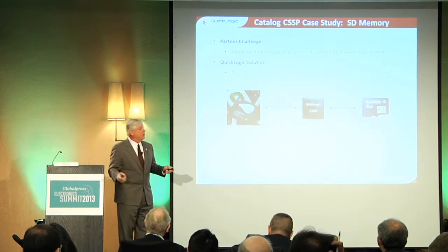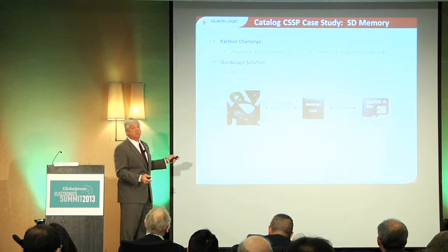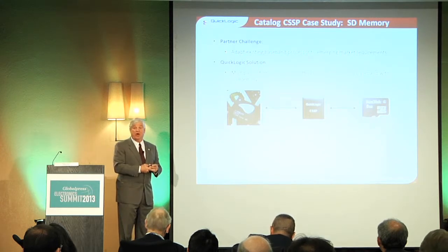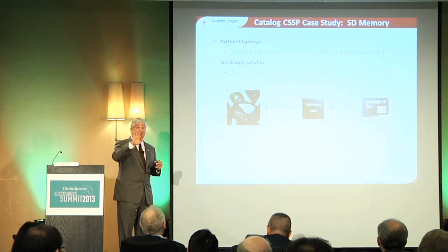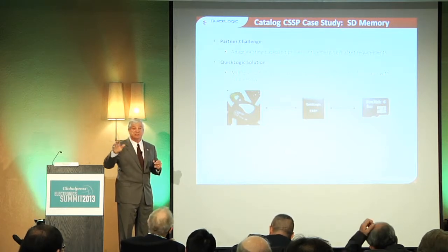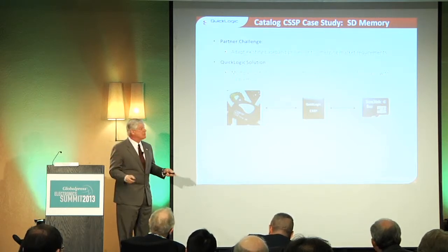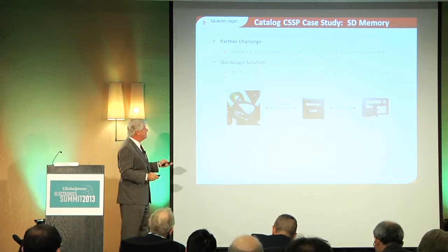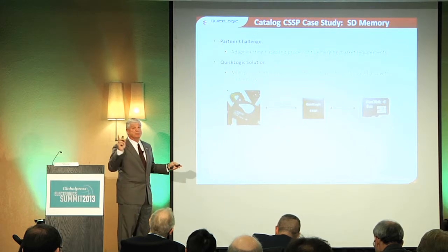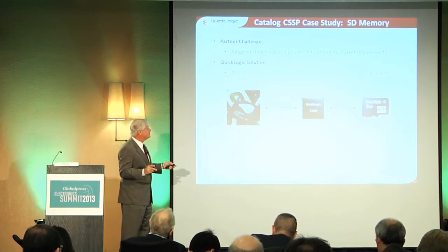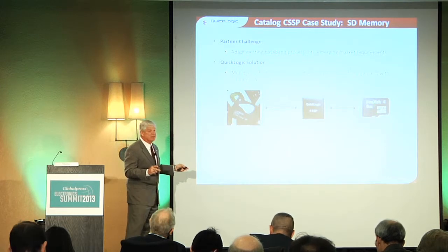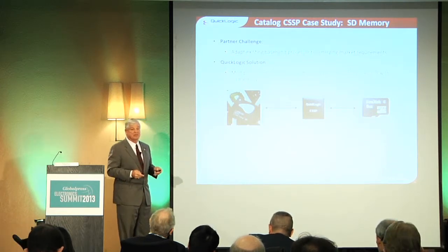In this case, we came up with multiple designs. Over 11 months, we came up with 4 different designs that enabled them to penetrate different customers. The base of this design was always a QuickLogic CSSP that connected to Icera's proprietary memory bus and provided them with SDIO connectivity to connect to various flash memories.